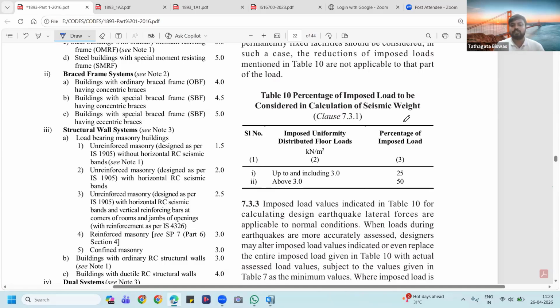But live load, which is the human load or any sort of movable objects load, could be variable during the course of an earthquake, because most of the time you might have seen that if an earthquake comes, people ask you to go outside of the structure or go downstairs. So it means the structure is getting reduced seismic weight in that case, right?